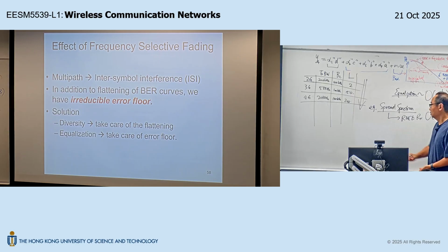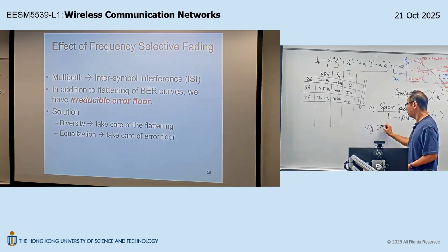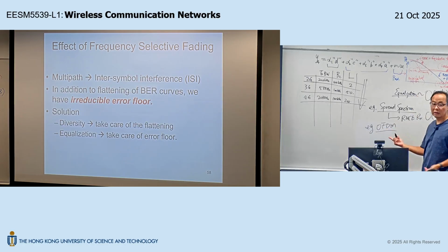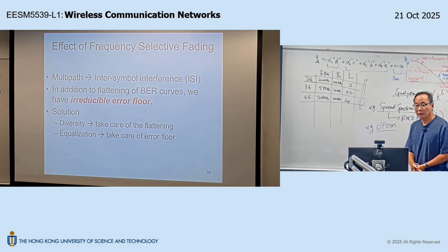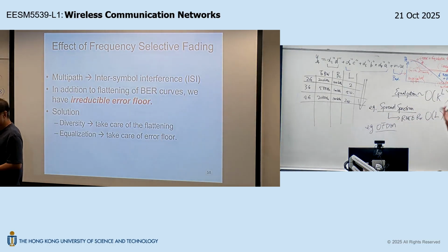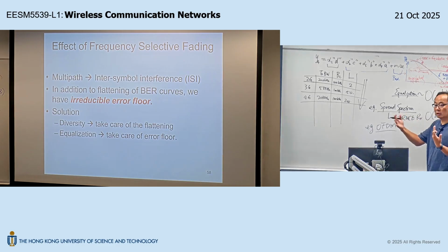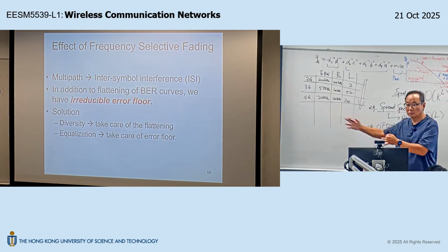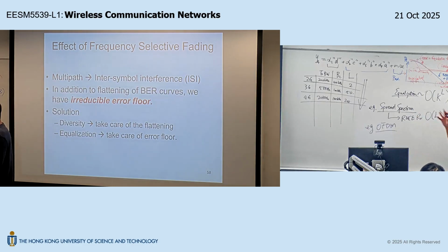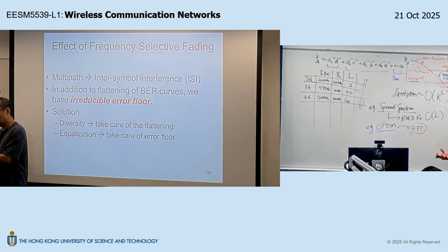Another example, OFDM. You probably again heard about this term, OFDM, which is the fundamental technology behind 4G. Similarly, in OFDM the transmitted signals are not just ordinary modulation symbols. They basically have this built-in IFFT structure. The modulation is done in the frequency domain, and then they transform back to the time domain to send out the waveform. So that is another built-in structure. And because of this built-in structure, the receiver of the OFDM system uses FFT. You can think of FFT as an equalizer at the receiver.